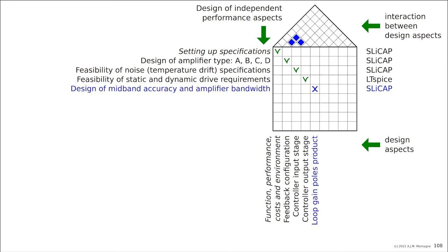If we have two inverting stages and we need to have a feedback, that would make a loop with a non-inverting loop transfer, then we would have positive feedback, and we need to do something about it. One way of doing something about it that we found is to use a balanced stage for one of the two stages or for both stages. But that does not necessarily change our conclusions, because we know if we go, for example, from a single CS stage to an anti-series stage, that we can have exactly the same performance if each transistor is 2 times wider, and the current in each transistor is 2 times more than that of the single CS stage. Then we have the same noise performance, and we have the same A, B, C, and D, and only the nonlinearity for the even components has changed.